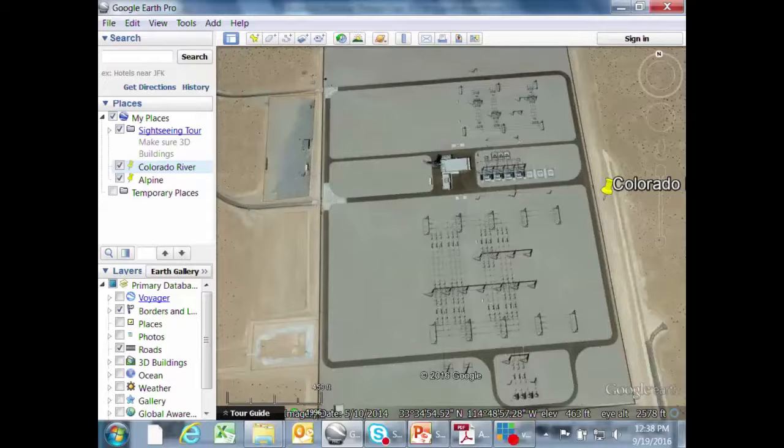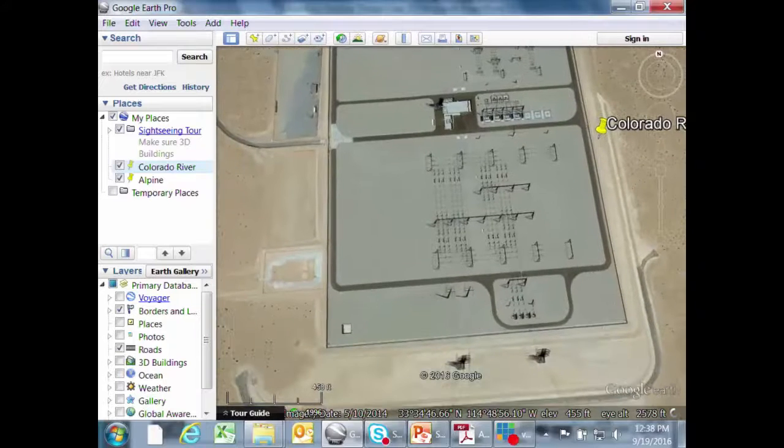It always amazes me how much the 230 is dwarfed by the 500 kV. These are the main buses on the 500, and that's 65 feet tall, and it has to be 65 feet tall to have enough room underneath it to connect to disconnect switches. These dead ends going across here are the 108-foot ones, and they have to be that tall so that the line conductors can span over the main bus conductors. Does that make sense? So you end up with some awfully tall structures.